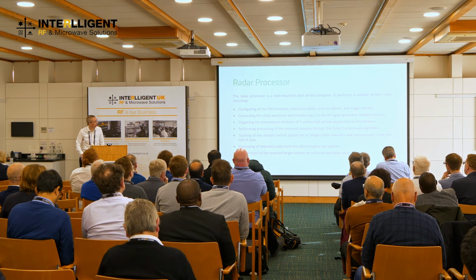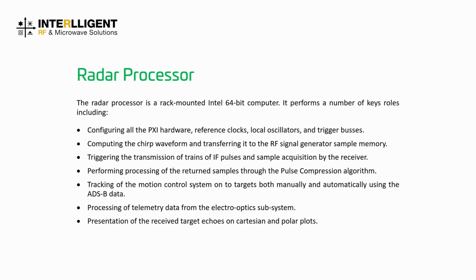So our radar processor computer does lots of things. It configures all the hardware, it synthesizes the chirp, transfers it up to the waveform generation box, also does all the receive processing signaling, and also does the tracking of the motion control system, as you'll see later.